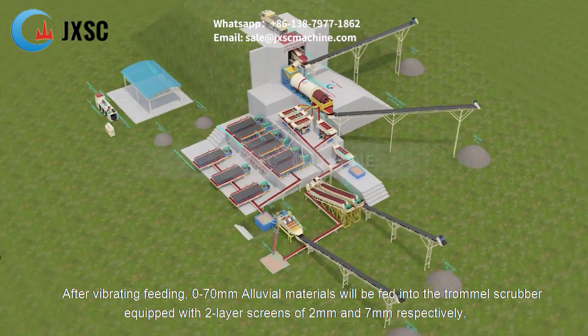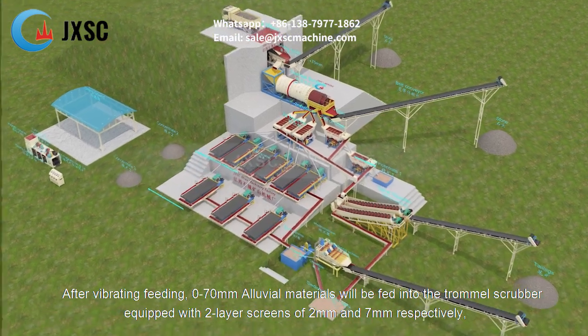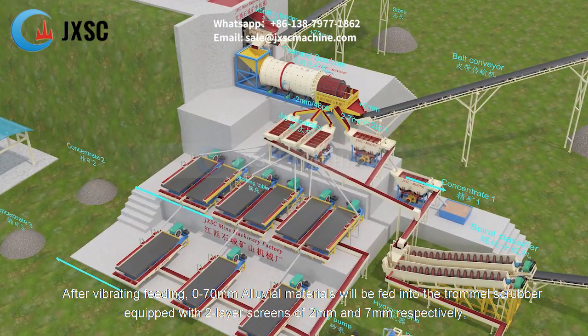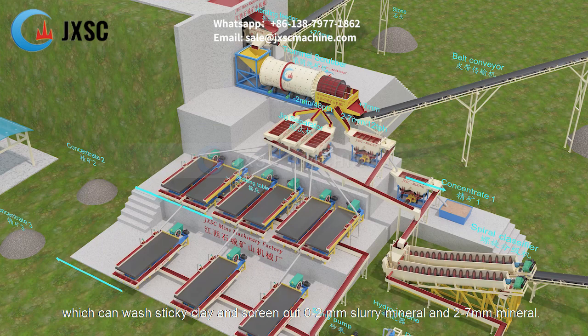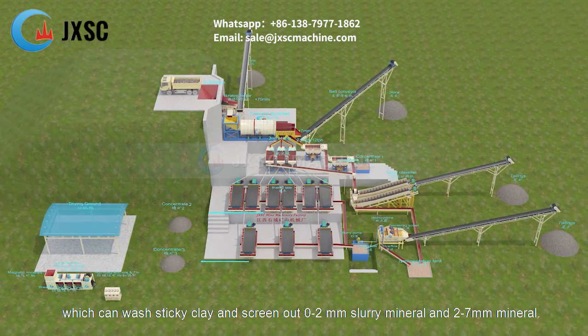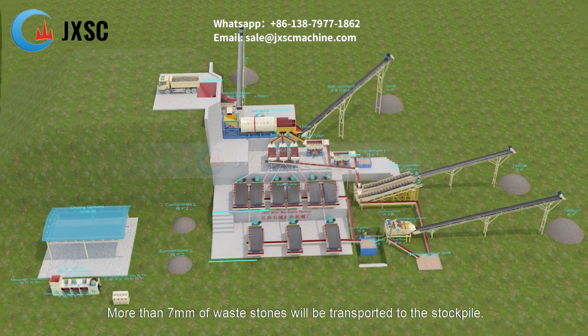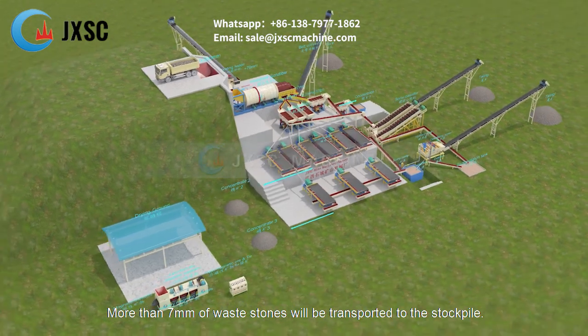After vibrating feeding, 0 to 70 mm alluvial materials will be fed into the trommel scrubber equipped with 2-layer screens of 2 mm and 7 mm respectively, which can wash sticky clay and screen out 0 to 2 mm slurry mineral and 2 to 7 mm mineral. More than 7 mm of waste stones will be transported to the stockpile.